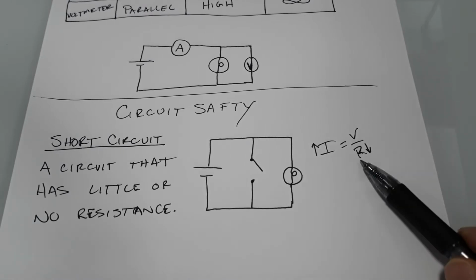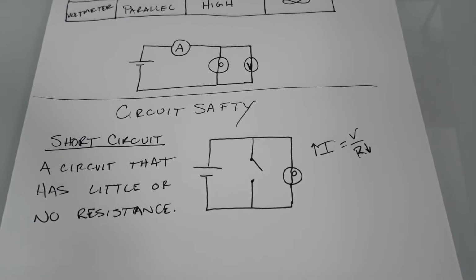And we're not talking about making a small difference. We're not talking about going from 5 ohms to 4 ohms. We're talking about going from 5 ohms to no ohms. Right? So there's no limit to how much current you can draw. And the reason that's going to become a problem is because, as we have talked about, when you pass current through any object, it's going to heat up. When you pass a lot of current through an object, it's going to heat up a lot because those random collisions with those moving free electrons delivering some of their energy to the atoms is going to cause those atoms to get so hot that they will reach hundreds of degrees.